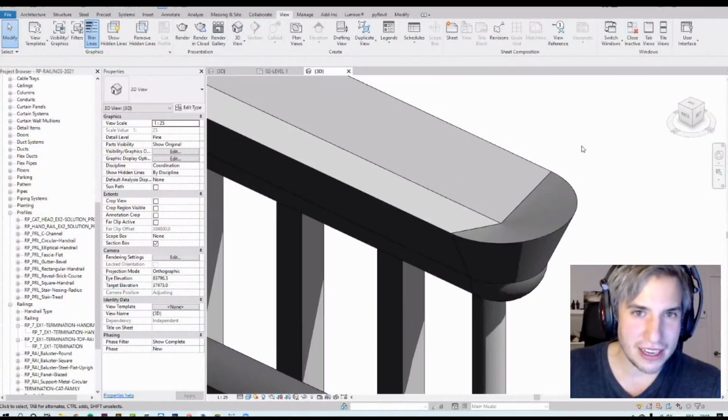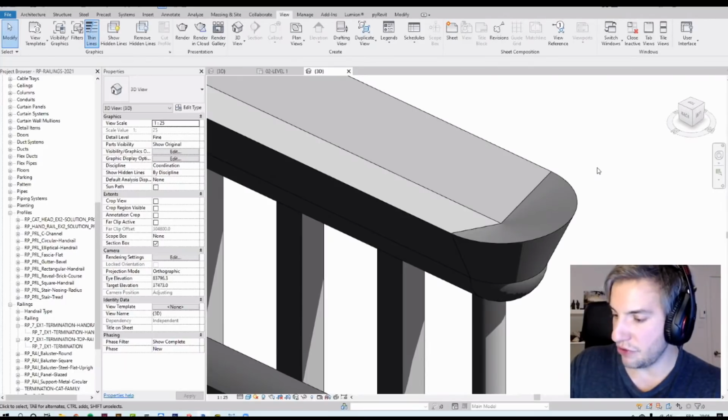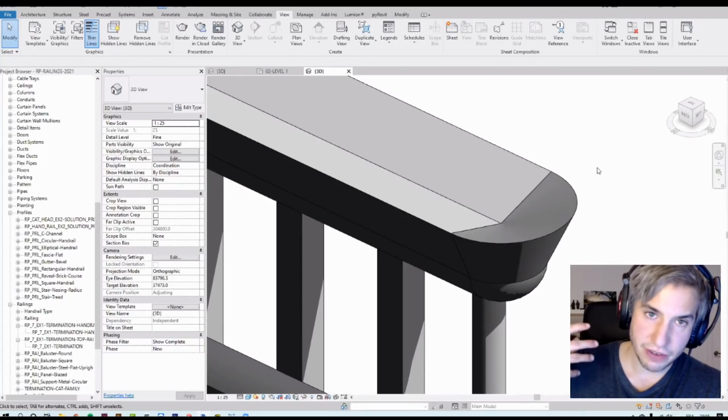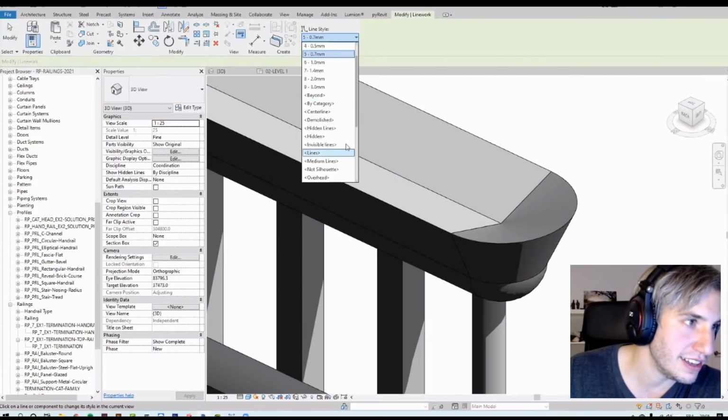Yeah, the thing is, you're always going to have a line here in 3D view. So although that joins, even if the material is the same or anything, it'll be. Yeah, that's right. Even if it's the same material, it doesn't join. But what I did, in the project, I have a few shaded 3D views, and it's kind of a cheat, but I've used the linework tool. Yeah, you just hide the linework. And I guess in theory, in the renderings, it won't look bad if it's all the same material. But I do use a few elevations in the sheets, and even in plan you'll see the lines, right?